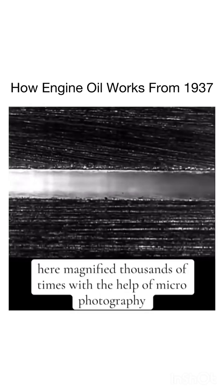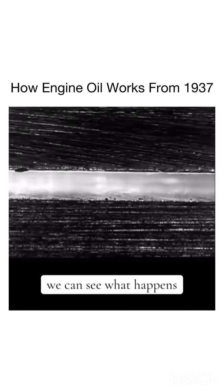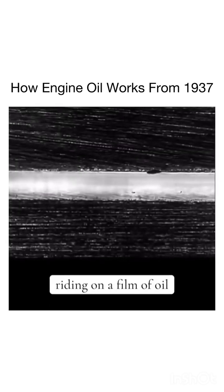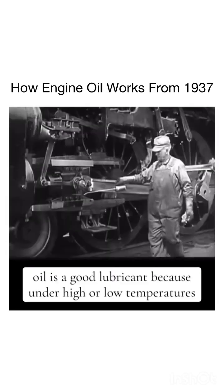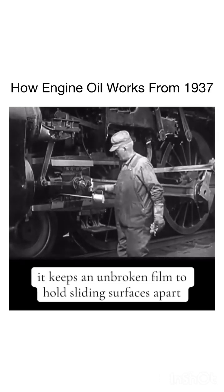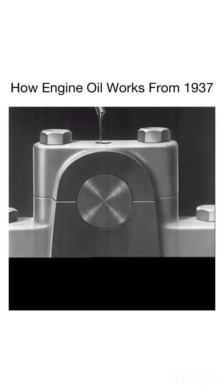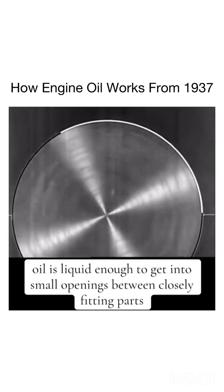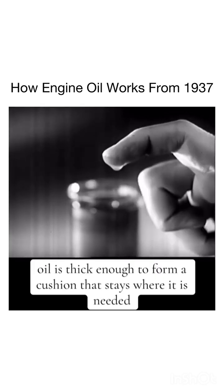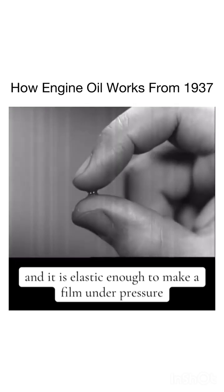Here, magnified thousands of times, with the help of microphotography, we can see what happens when a metal surface glides over another surface of metal riding on a film of oil. Oil is a good lubricant because under high or low temperatures, it keeps an unbroken film to hold sliding surfaces apart, and it won't evaporate. Oil is liquid enough to get into small openings between closely fitting parts. Oil is thick enough to form a cushion that stays where it is needed, and it is elastic enough to make a film under pressure.